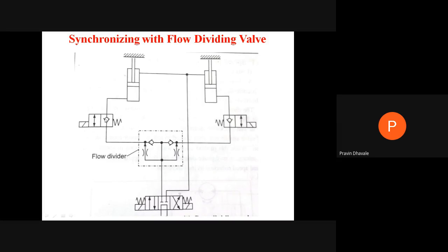So this flow path will be connected. Are you getting? So whatever the fluid from the piston head side, now it is passing to this. From this, instead of going through this flow control valve, it is directly passing through this check valve. It allows the flow, free flow in this direction, left to right, from here and from here to tank.